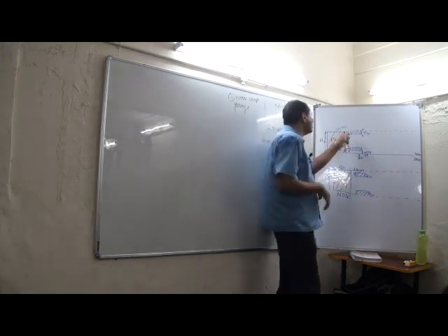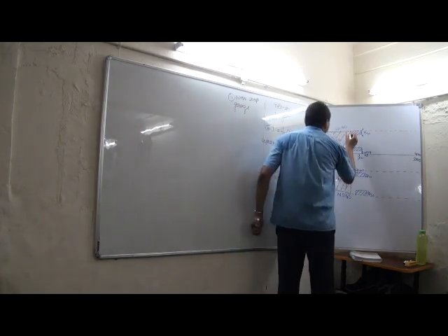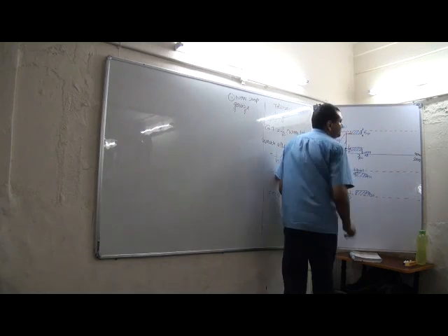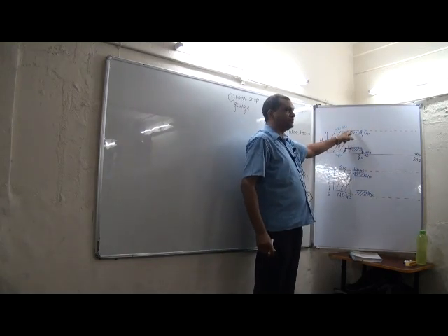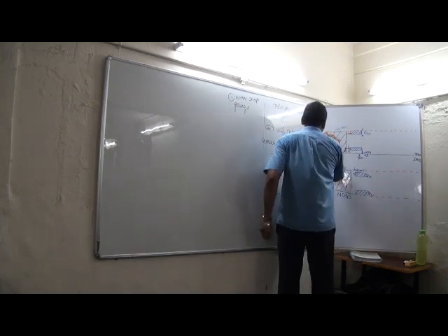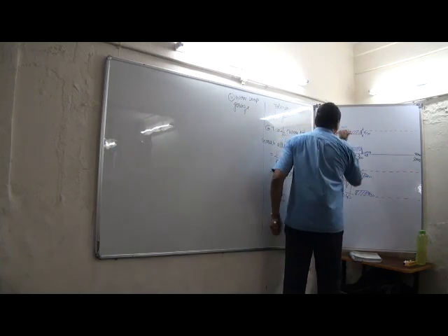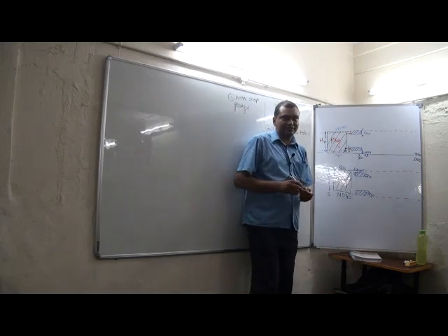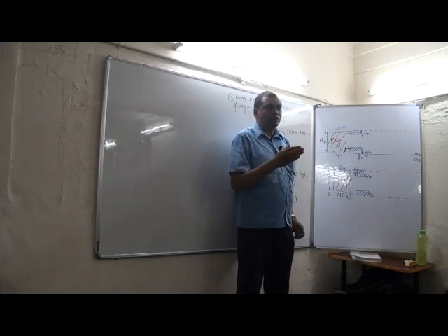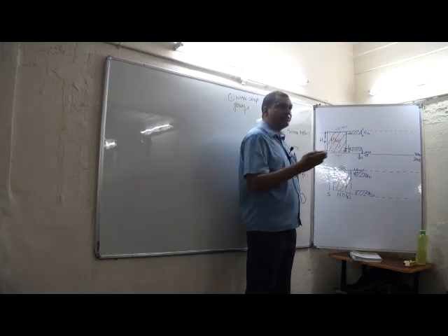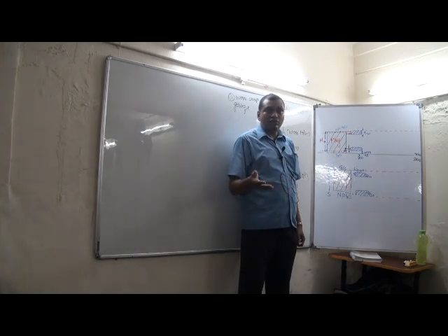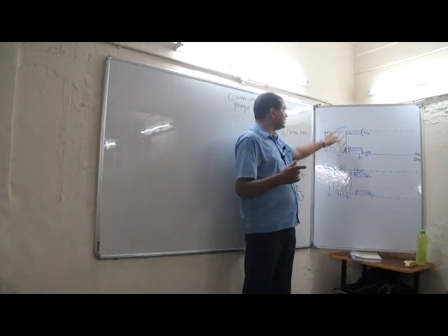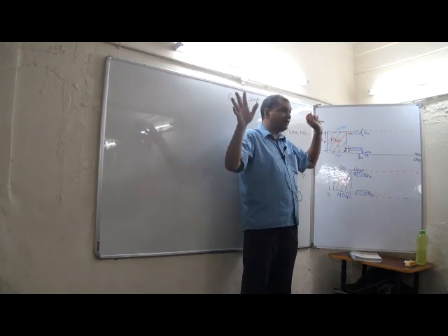The same thing will happen on the no go gauge side. Let us say this is the size of the no go gauge, because that can appear anywhere in this range. And let us say this size of hole appears to the no go gauge. The no go gauge will enter into the hole. So according to the no go gauge, the hole is oversized, but the hole is well within the tolerance.